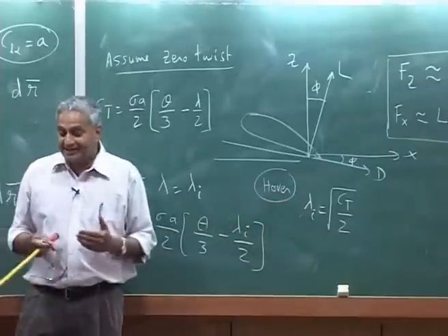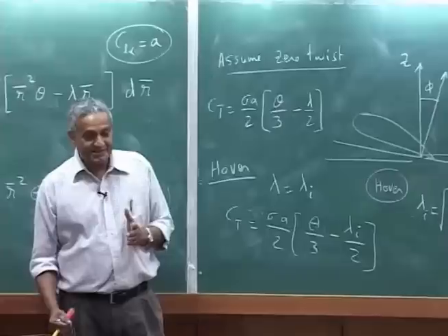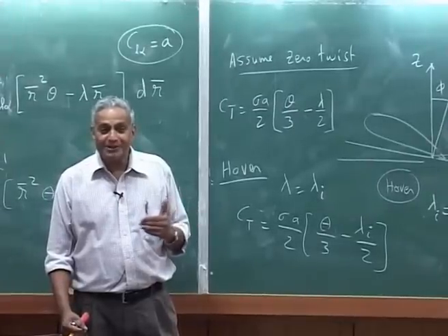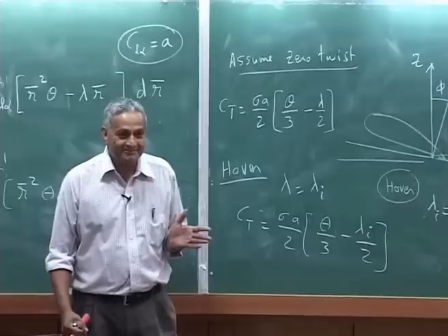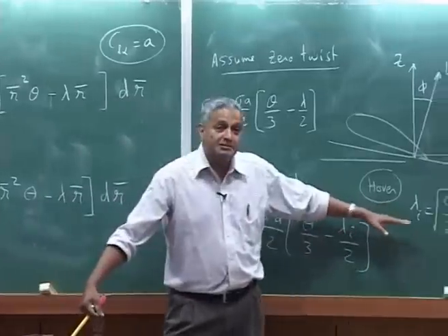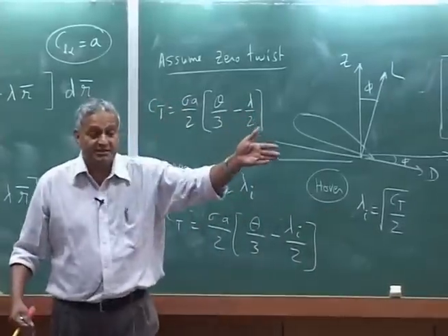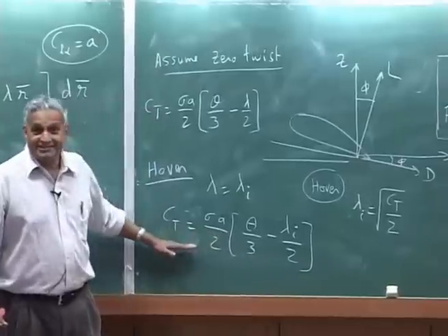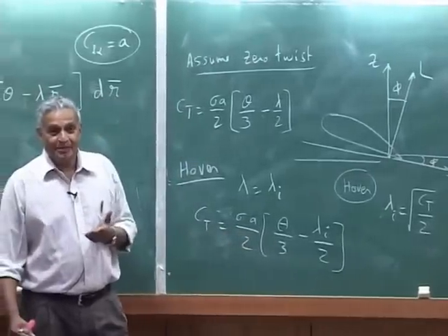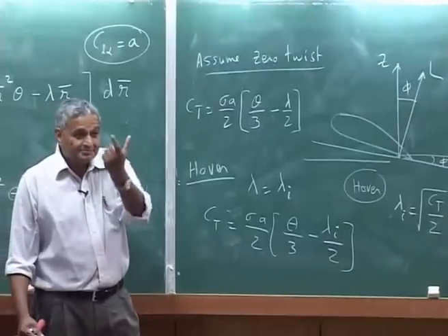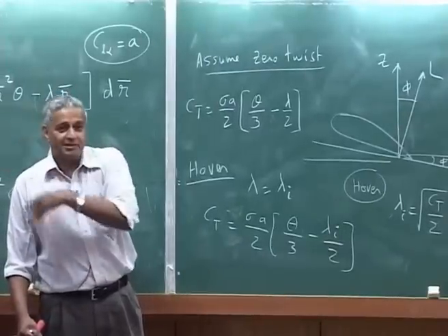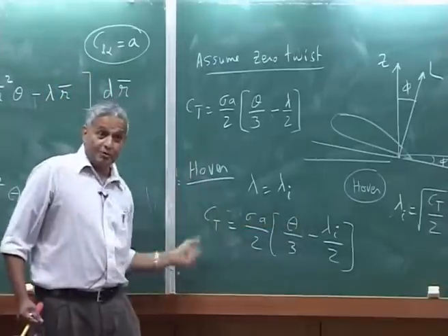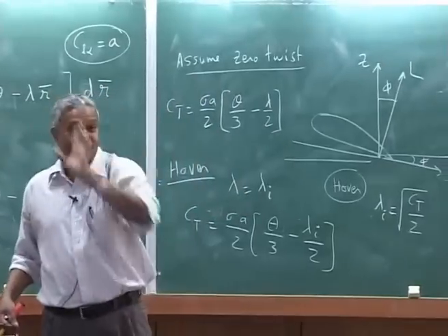Now in helicopters, you understand that you cannot live with only momentum theory, or only with blade element theory. You can replace the momentum theory by some other theory, vortex theory, but blade element theory is essential. So you always have two theories, either you take prescribed wake or free wake, any analysis, and then I get the inflow, then use that inflow, put it here, get the thrust, then go back again to see whether that thrust gives me that inflow.